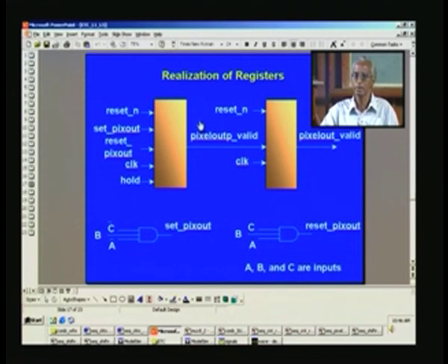So, that means you can process 1024 by 768 pixel color pictures, motion pictures at 30 frames per second, and for that you also have to have another signal indicating when that pixel is valid, and for that I had to generate this one. How is it generated? In fact this generation is already done here at this specific edge of the clock, that is one clock prior, beforehand it completes.